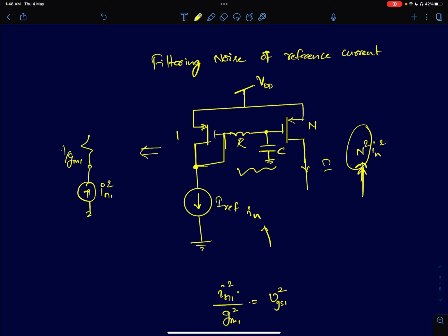If you have a problem with the noise, the simplest solution is to add and cancel it out using filters. Now, if you recall the beginning of the lecture, I said the operation of a current mirror can be seen as a two-step process. The first step is whatever is applicable to DC is also applicable to noise. So the noise current IN flows through the diode connected MOS and it creates a noise voltage Vn.